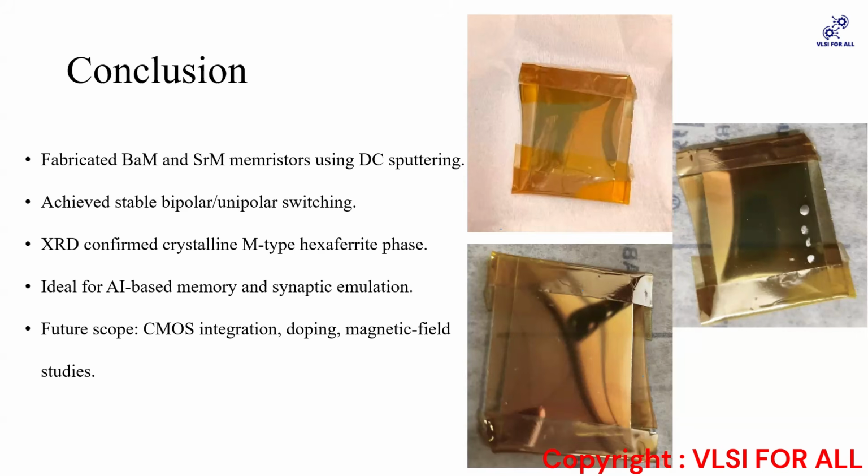the target gets hit by the current, and it was not able to create a uniform image, and eventually the target gets damaged. While the target gets damaged, we are going to have a huge loss of devices, and eventually a lot of material is lost. And this is the reason why we are not going for RF sputtering, and we are just moving to DC sputtering.